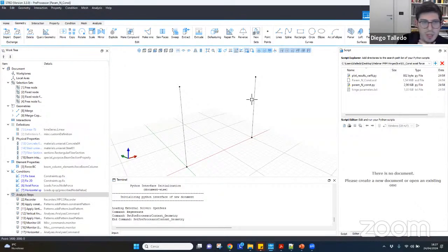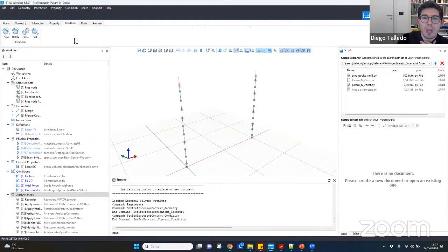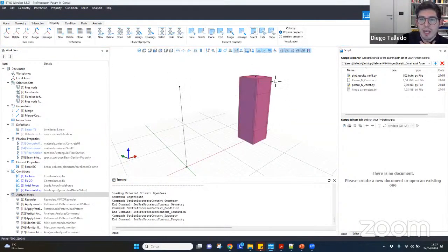I will show you just in a second the details of the geometry. From the property, you can see that this element on your right is already defined. Basically, this is the column modeled with the classic fiber approach, actually with the finite length hinge approach. And so you will see the model that it's already at this stage. And we prepared the geometry for the hinged approach, and we will create it together right now.